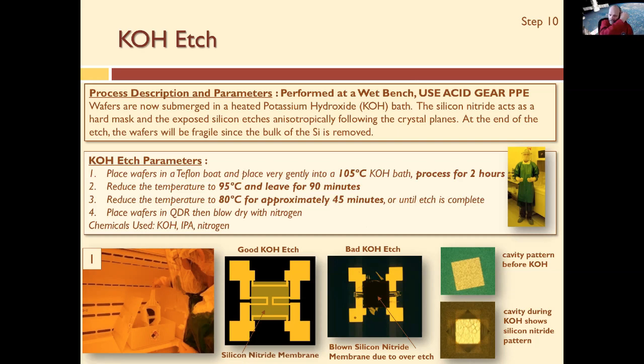So once we're done with the KOH etching, we do a really soft rinse, right? And then we dry it with a nitrogen gun, very soft flow of nitrogen to dry it off. So we do a water rinse typically, and then an acetone rinse, right? And a methanol rinse, and then you can dry it with your nitrogen gun. And that way you don't leave too many defects behind.